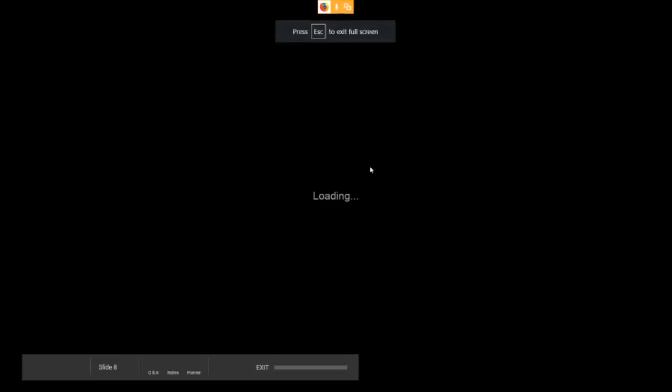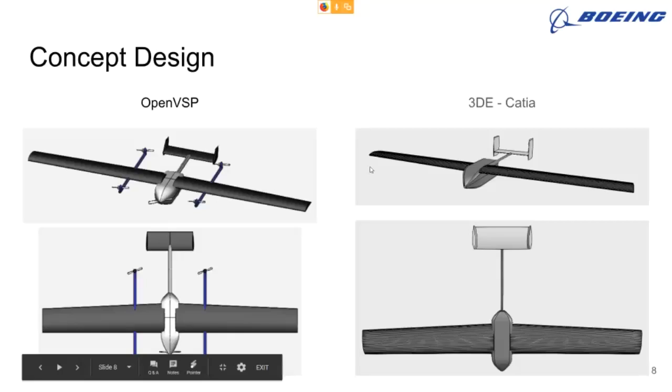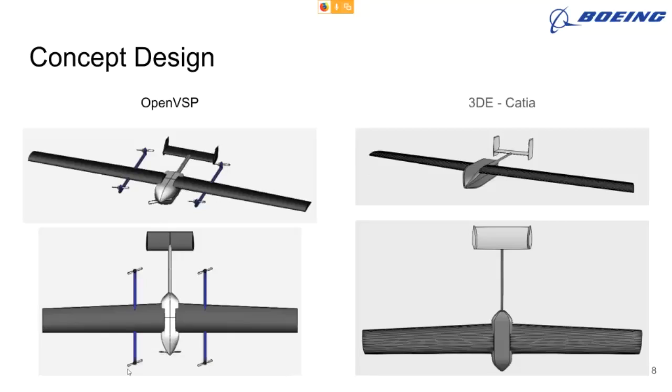Also, in terms of the camera system, while we do have a puller nose in the front, we were planning to have some sort of either cutout or plastic dome that the camera could see out of below the nose, because having the camera in the very tip of the nose would not be very effective in terms of surveillance, because you will only catch a very small part of the land area, and it makes more sense to have it angled downward. So we were planning to try to fit it underneath, although if that does not work, we could consider putting it in the back.